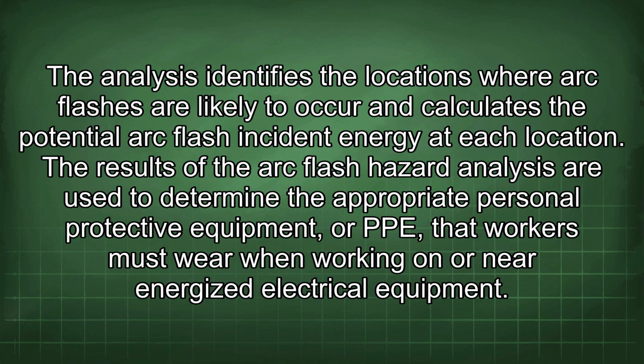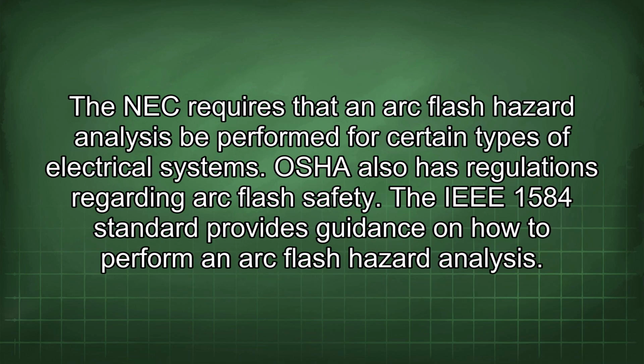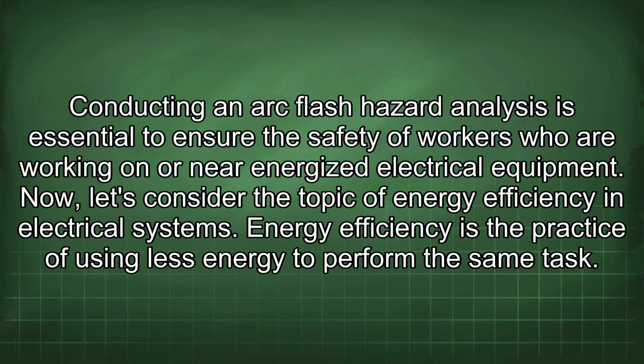The results of the arc flash hazard analysis are used to determine the appropriate personal protective equipment, or PPE, that workers must wear when working on or near energized electrical equipment. The NEC requires that an arc flash hazard analysis be performed for certain types of electrical systems. OSHA also has regulations regarding arc flash safety. The IEEE 1584 standard provides guidance on how to perform an arc flash hazard analysis. Conducting an arc flash hazard analysis is essential to ensure the safety of workers who are working on or near energized electrical equipment.